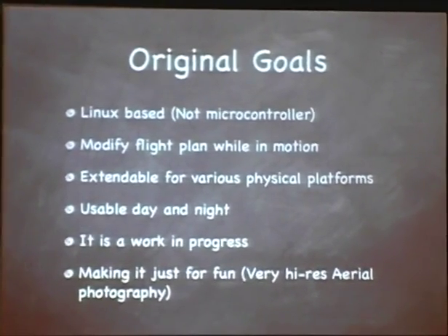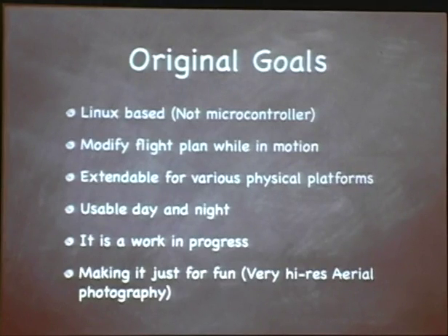We wanted it to be usable during the daytime and the nighttime, because a lot of the other projects use infrared to keep the stabilization of the plane. It tells the sky from the ground by infrared light. When you get over water, the light reflecting back confuses it, and at nighttime it doesn't work because there's not enough infrared light. It is a work in progress, but it's progressing pretty well, and it is pretty much just for fun. There's no commercial side to it or anything.